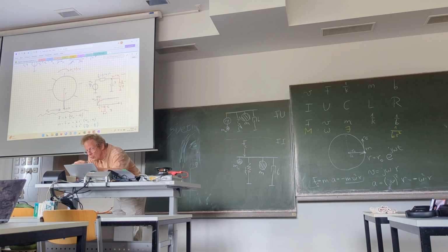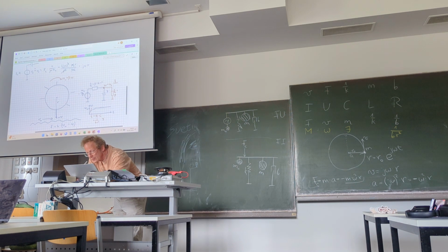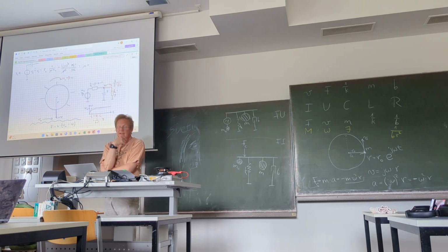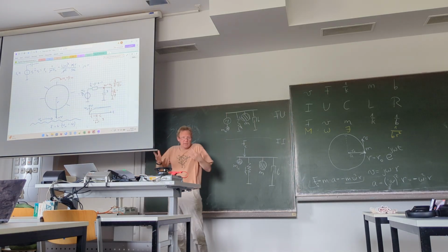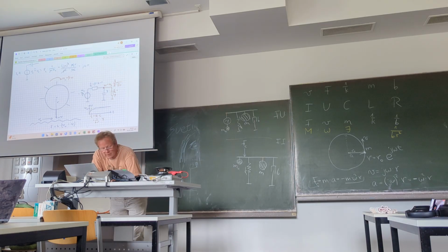So actually this is 1 over beta in the numerator, and in the denominator we get the sum, so it's 1 over beta plus 1 over b times r squared. Again, something I would never have guessed just by looking into the mechanical model, but we can apply all the electric laws, and so it must be true.